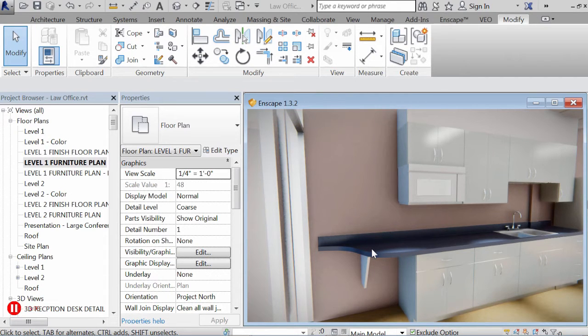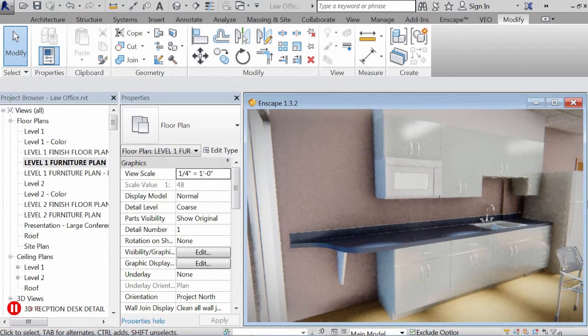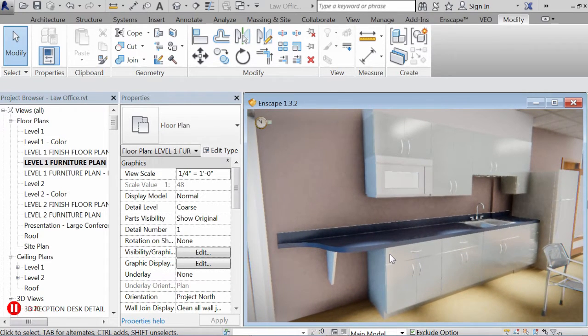Rather than having a countertop just butt into the glass, it curves to a smaller profile. So an in-place family was used to develop that. And you like doing that for one-offs. If this was a repeated, multi-story building, you might build a family component. Otherwise, correct, one-off.